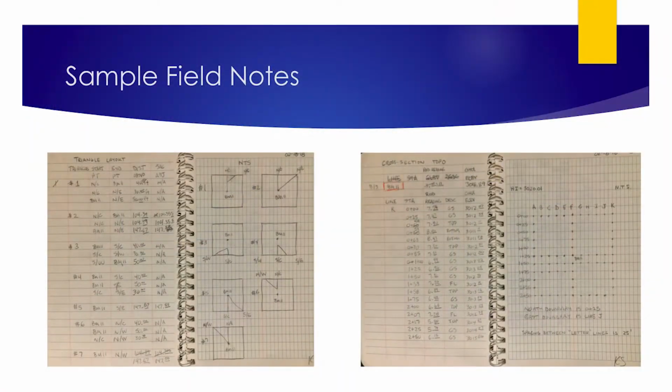So I was responsible for taking the field notes, and field notes, as we all know, have to be accurate and clear. And the importance of that in accuracy, that doesn't mean accuracy of numbers. It means accurately reflecting what the work done that particular day by that crew. And you have to include sketches, and the sketches need to support the data that you collected.